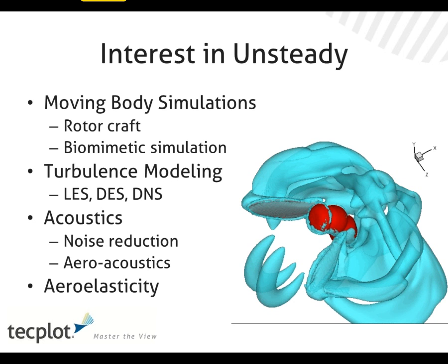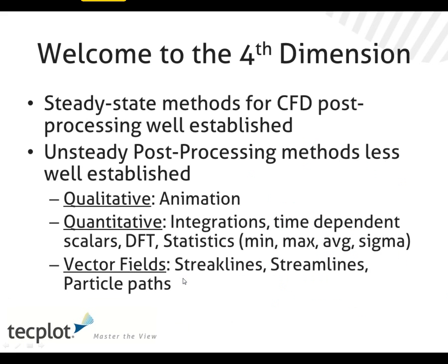I know that there's been a tremendous amount of work Boeing's done with the 787 to reduce noise so that the plane can be validated in a number of different airports. Yeah, absolutely. Acoustics is often generated by the aerodynamics of the plane, and hence the aeroacoustics. And so these simulations typically use very high resolution CFD methods, and highly resolved in time as well.